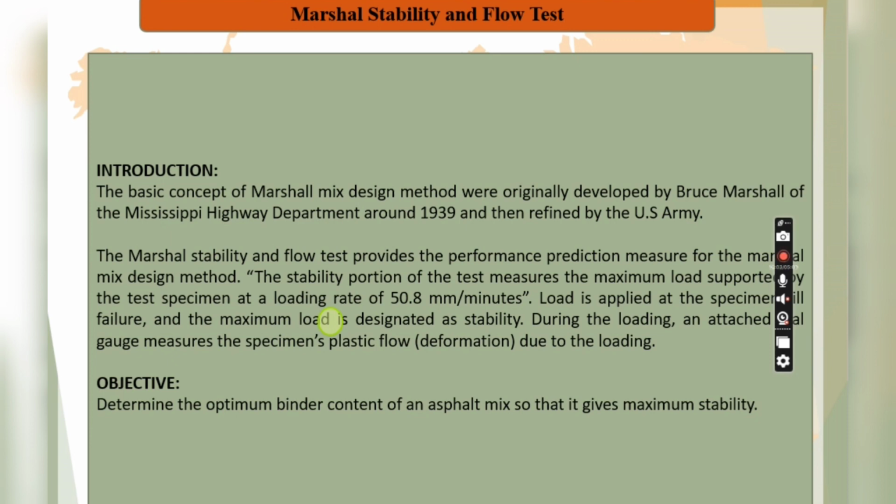As I said, the Marshall stability test is applied to check the resistance to plastic deformation of bituminous material and its maximum strength. So what is the objective? The objective is to determine the optimal binder content of an asphaltic material that will give maximum stability.